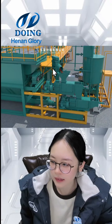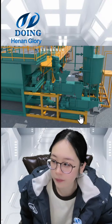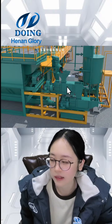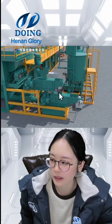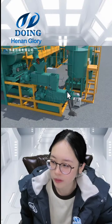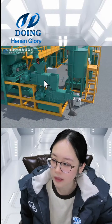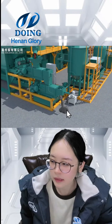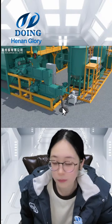And we can see these two pressers. What is it? This is the double screw palm presser, right? So the first presser will push out the impurities, and the second presser will press the impurities a second time. And then here come the fibers. I think fibers with the kernel, right?